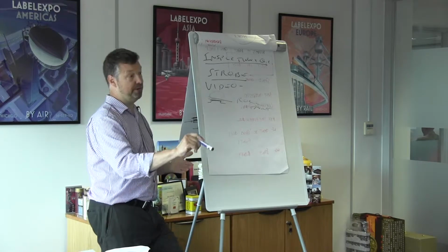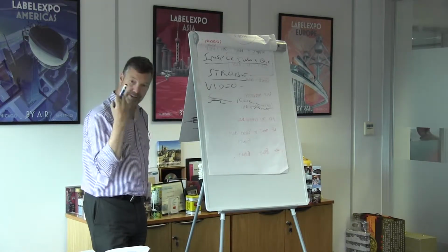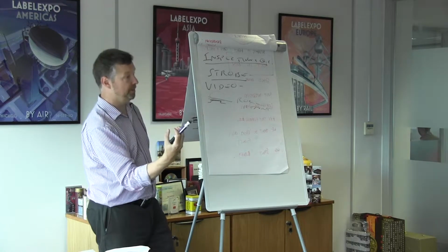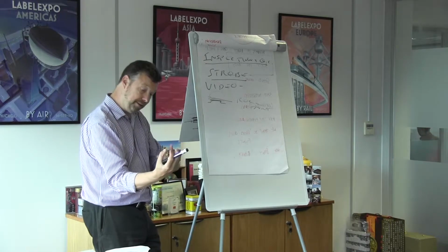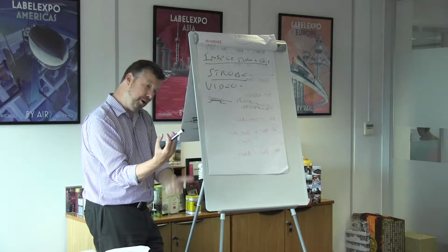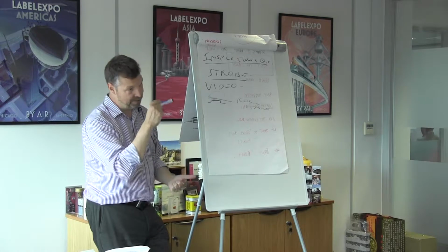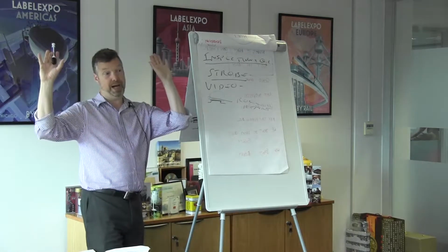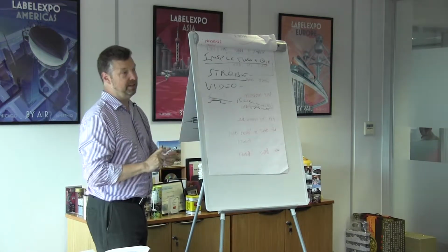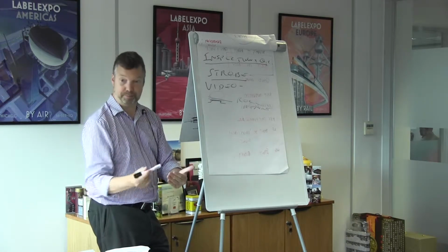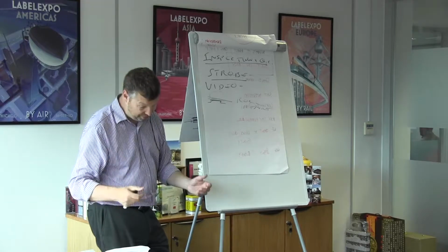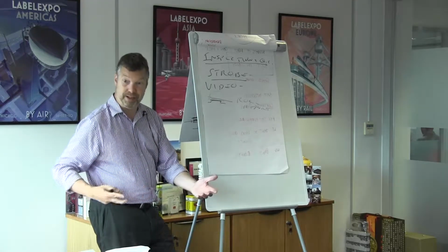It then goes directly onto that roll, that digital file now controls the Rewinder. Okay, so what you've done is every time you've got a defective label that has been marked, the LinkJet just barcodes it on the back of the web. So when it goes onto the Rewinder, it's all hands off, right? No one needs to touch it. When it gets to that part of the web, it reads the barcode and just stops it. So all the operator does is just get the scissors and splice it.